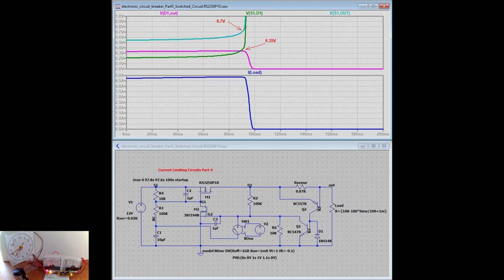In the case of the circuit presented, the 5 amps limit times the RDS on resistance of 0.07 ohms equals 0.35 volts, green line showing the VDS voltage drop. 0.7 volts minus 0.35 volts equals 0.35 volts, pink line showing the voltage drop on R-sense resistor to trigger the circuit. A 0.07 ohms R-sense resistor will limit the current to 5 amps, as shown in the picture, cyan chart showing VDS plus R-sense voltage drop of 0.7 volts.